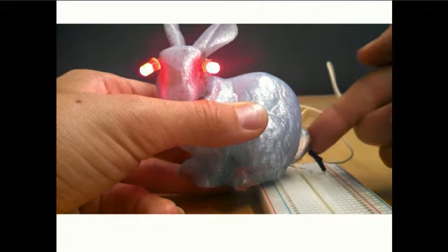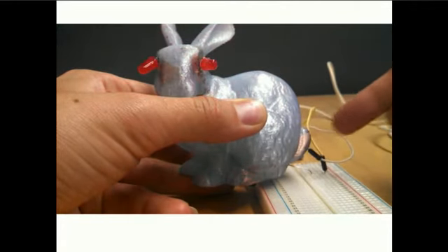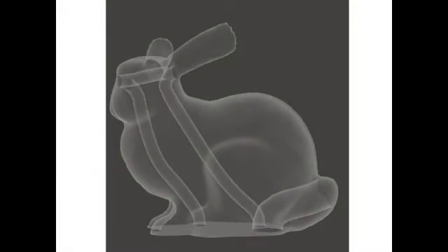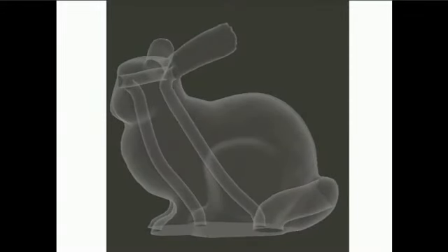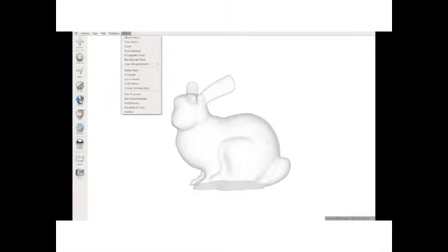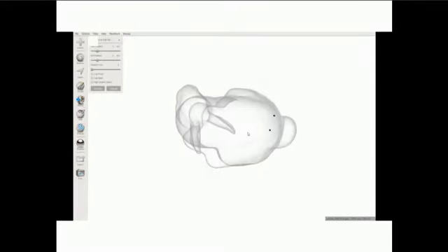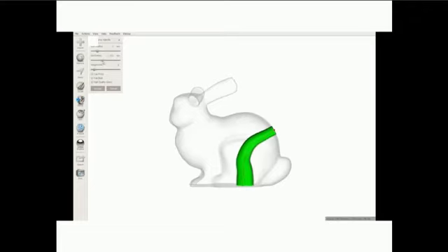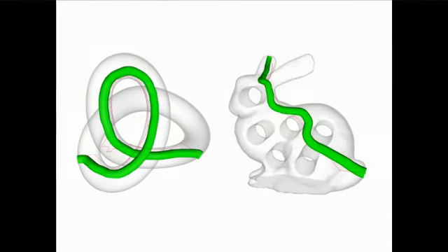Can we just print this in one go, and then you just stick all of your electrical components on the surface in the end? Basically, the idea here is printing 3D circuit boards inside of objects while we fabricate them. We did this project together with Autodesk. We have a design tool that allows you to specify surface constraints: I want to connect this place on the surface with this other place. We then automatically create the connectivity on the inside of objects, and you can do this with arbitrarily complex geometries.